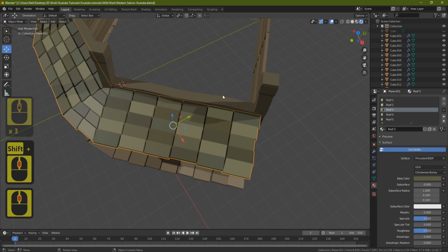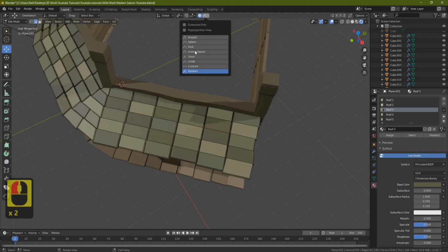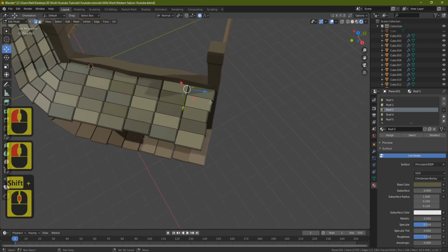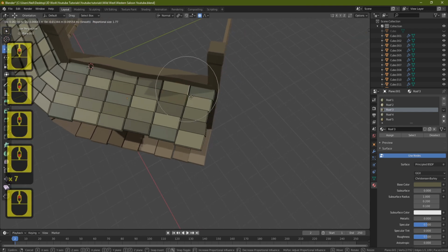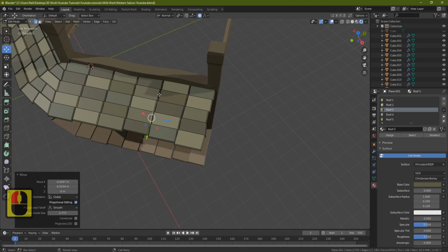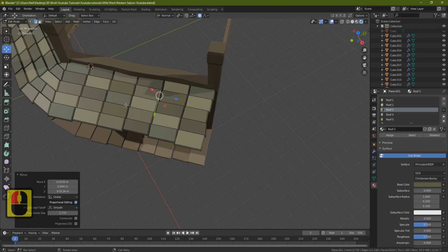And now, of course, the last one we need to do is to come to Edge Select, Proportional Editing, and I find first of all to do the smoothing. So grab them like this, put it on normal on this side, and let's press G and bring it out just a little bit. To do the proportional editing on smooth first, and then when you've done that, then you can work with the randomize on.